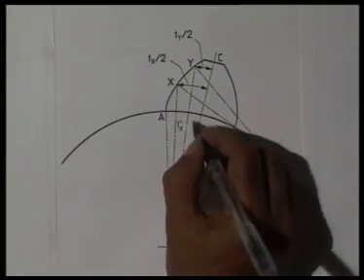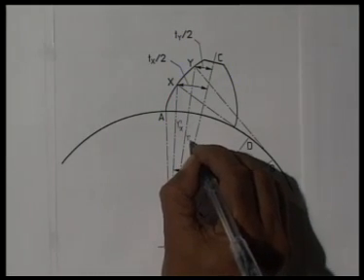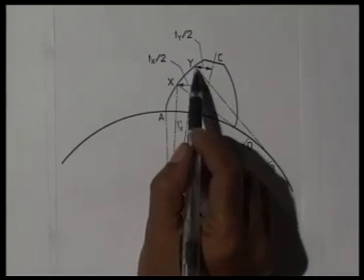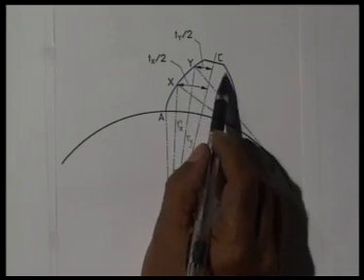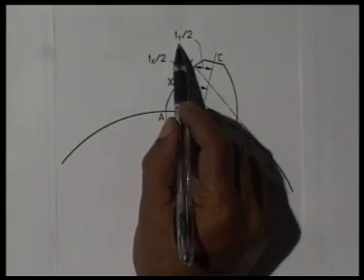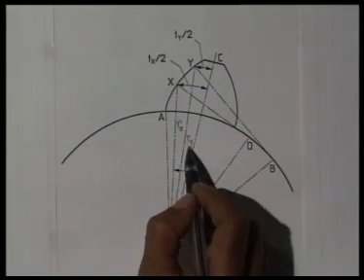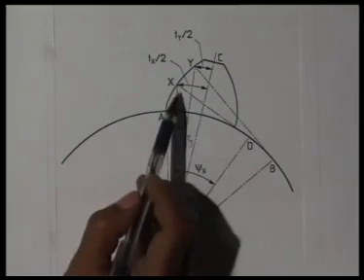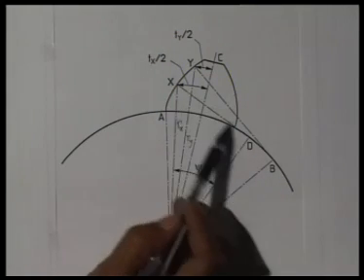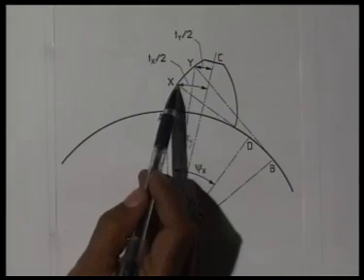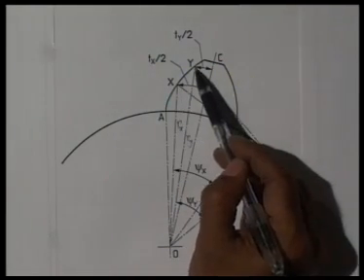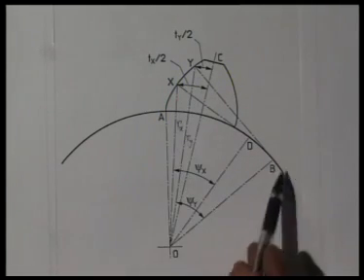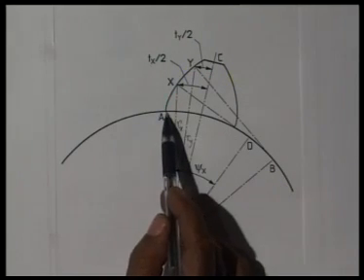Then when this polar distance changes from Rx to say Ry, I get to this point y, and I want to find what is the thickness of the tooth at this level, that is Ty. So Tx is given, I would like to find Ty, and Rx and Ry are given. To do this, first we note when the involute was at x, the string is dx. This is the length AD, which has become dx. And when we come to the point y, the string is represented by by. This is the tangent. By is the same as the arc length AB.